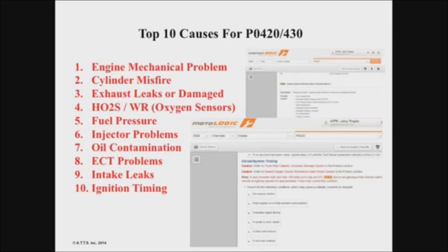And the number one problem is engine mechanical problems. It's like if this roof was sagging, we don't start throwing a new roof on, we start with the foundation. And some of the things that we forgot is going back to the basics. Does this vehicle have a good engine? And I see this a lot. I do a lot of state emission programs where people will throw a new mass airflow sensor, new oxygen sensor. They're trying to throw all these parts at the car, but they got a mechanical problem.